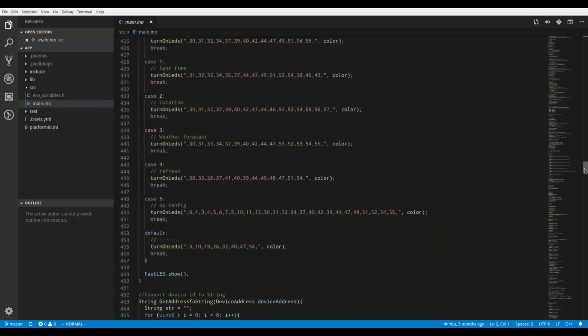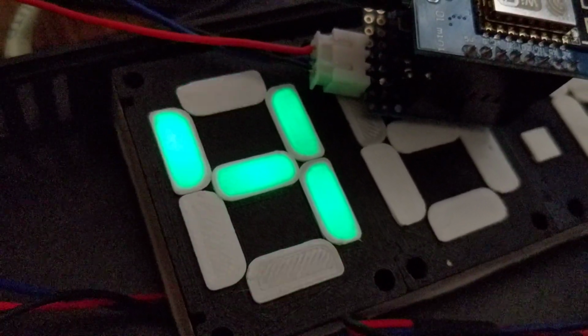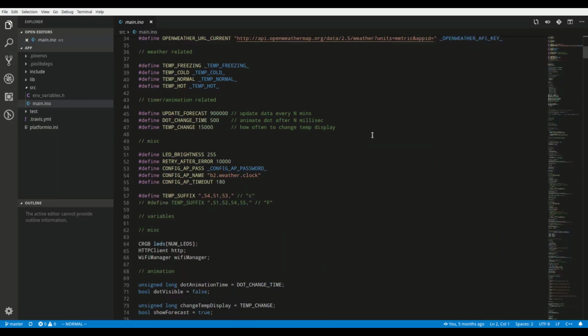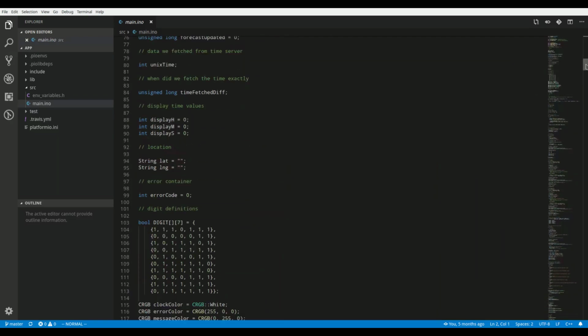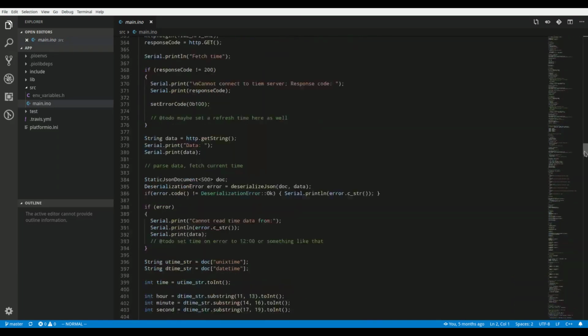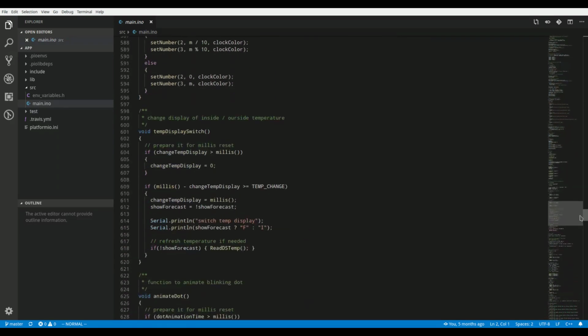I wrote and tested the firmware software in modules. First, I wrote the part which handles the display. On this picture, you can see how the LED strips are chained together. After this, you can address them as a single array in the code, and they only use one I/O pin. Writing the rest of the firmware was also really fun. I mostly used free APIs to fetch the user's external IP address, location based on that IP address, and weather forecast based on the location.